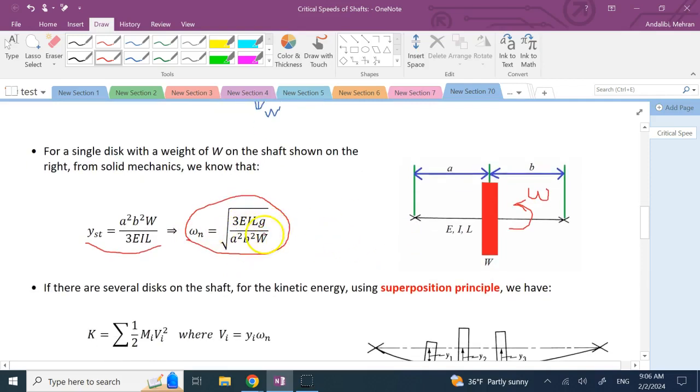So if we want to run this omega, it had better be quite a bit bigger than, I don't know why my stylus does that. It has to be way bigger than this formula here, okay? That is the critical speed. We don't want to run it.